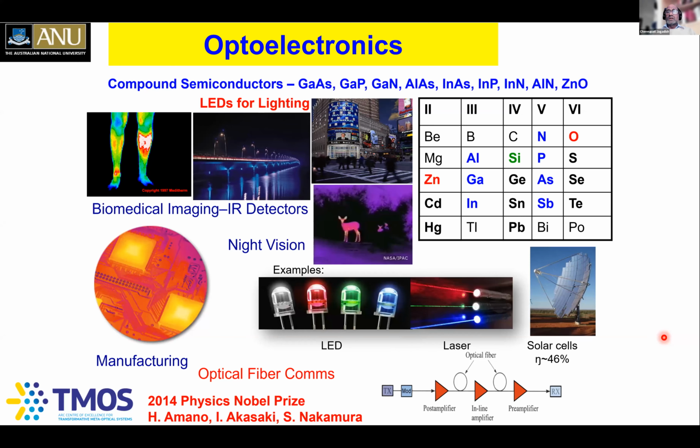So really, it turns out, though silicon is an excellent semiconductor for electronics applications, it is not a very good light emitter. Still, silicon is also nowadays used for lots of silicon photonics applications, and Professor Shankar Sauraja has given a talk earlier to you. But unfortunately, silicon being an indirect bandgap semiconductor, it cannot emit light. If you want to get efficient light emission, you need to use direct bandgap semiconductors, which are made out of these III-V compound semiconductors, group 3 and group 5 of the periodic table: gallium arsenide, indium phosphide, gallium antimonide, gallium nitride, aluminum nitride, indium nitride, and combinations of these materials.